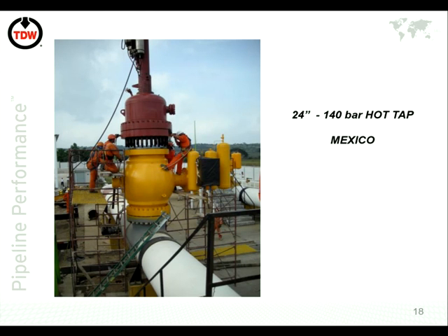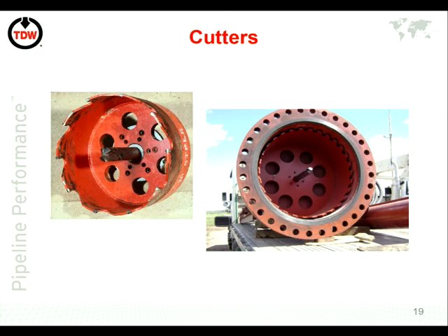These are the cutters we talk about, and as I say, the cutter itself is no different to what you would buy in B&Q, although it's a bit more extensive and a bit more rigid. The cutter is the size of the hole that you want in the pipeline. But every one of them will have this pilot drill, and the reason is that it allows the cutter to go in exactly the position you want. It also has a secondary, very important function, and I'll come on to that a little bit later.